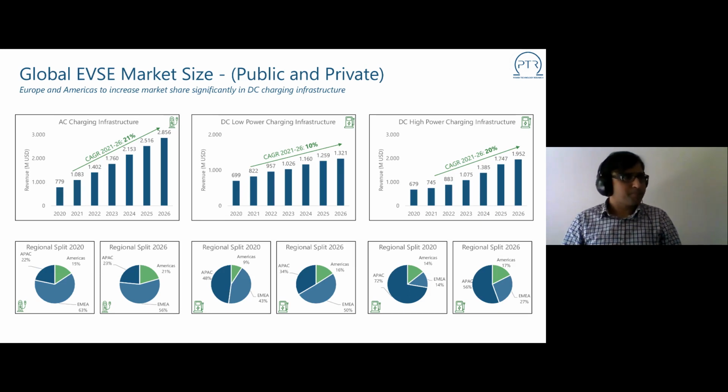We cannot ignore AC charging infrastructure because, as we touched on briefly, where a combination of chargers is installed in a depot setting for light commercial vehicles, the model which has been successful so far is AC 22 kilowatt chargers. Often hundreds of charging points are installed in one place, so having a strong enough grid on the back end to support this charging infrastructure is very important.